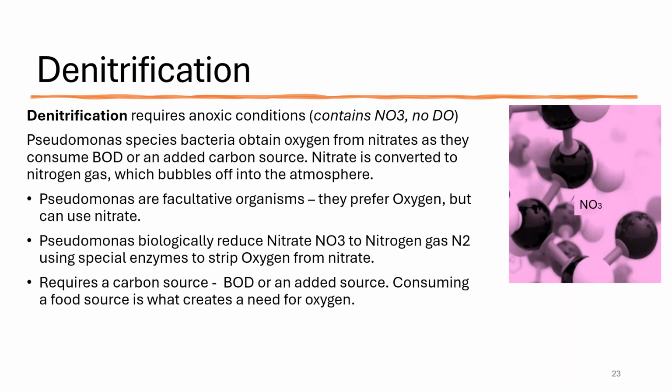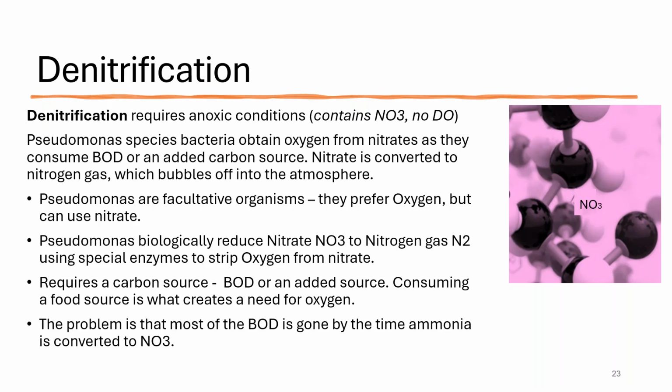And they do require a carbon source. And so in the treatment train, near the end of the oxidation tank or the aeration tank, if you think about it, you get to the end of the aeration tank and the BOD is gone and you have nitrate. So you basically have a situation where you have nitrate, but there's no BOD to consume. So that creates a little problem for us. And that's what we're going to talk through next.